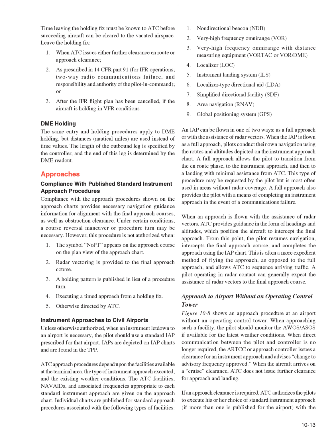DME holding. The same entry and holding procedures apply to DME holding, but distances, nautical miles, are used instead of time values. The length of the outbound leg is specified by the controller, and the end of this leg is determined by the DME readout.